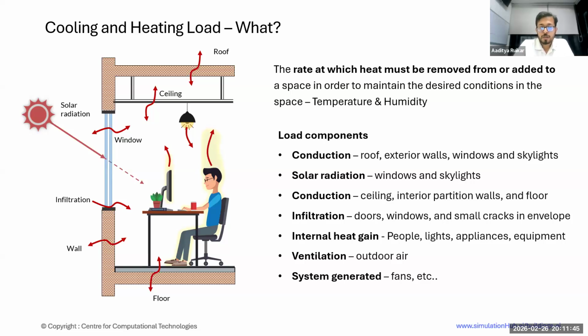Then ventilation: whatever outdoor air you bring in also adds heat or cold air from the outside, based on your scenario. Then system-generated things like fans may add heat, or there are inefficiencies that also add to heating loads. So all these loads are what the HVAC system has to counter with some operation to maintain your space. That is nothing but your cooling or heating load.